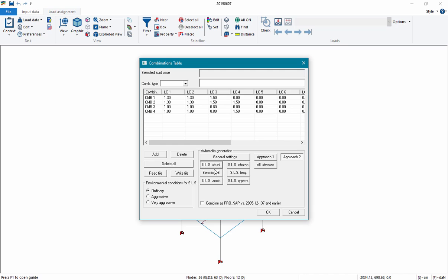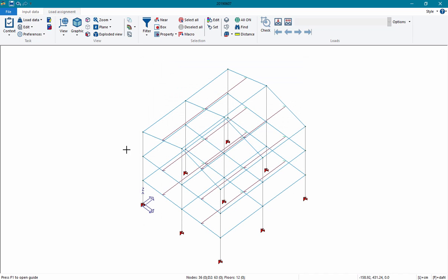The first one is for load combination with dead and live loads. The second one is for seismic load combination. This command provides the load combination for fire-bearing capacity. So if we don't have to do this kind of analysis, we can skip this command and define the combination in serviceability limit states. Okay. Once the combinations are defined, we can run the analysis.